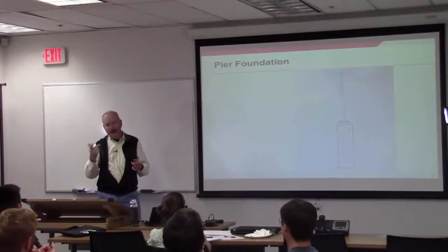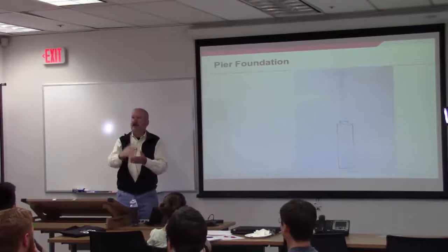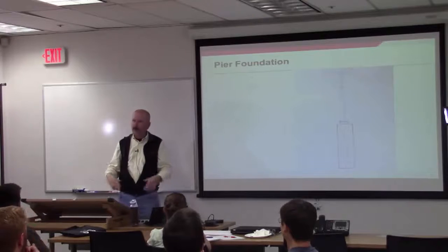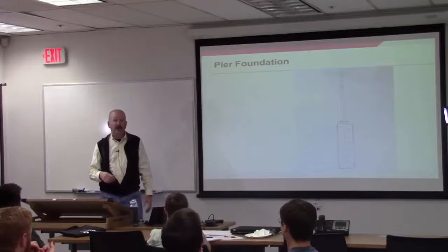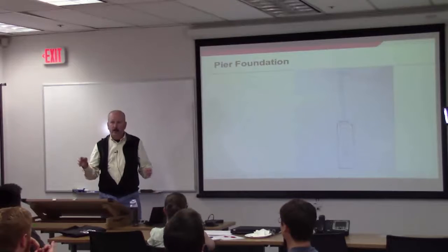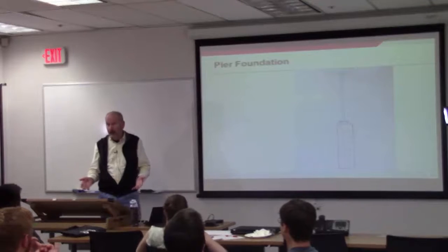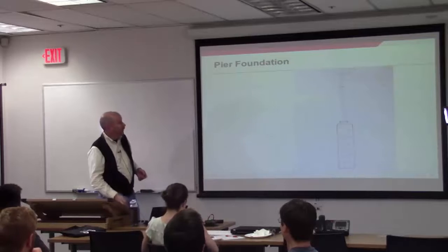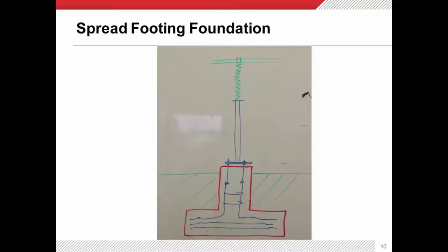We designed one. This is a Portland General project years and years ago, and they didn't give us a soils report, so we did what we had done on every other project. We had done the piers, and we went out there. The first day they called us out to the field, and they're all hot and bothered and mad at us because we had designed a system that you simply could not work with. And we just said, well, you didn't give us a soils report, so, anyway, when you have that, here's what you do. You do a spread footer.